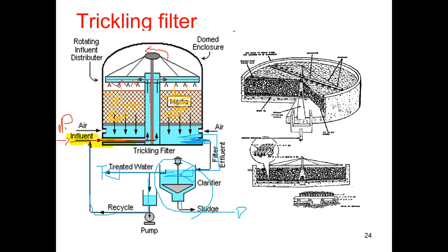And you know this is an aerobic biological reaction. That means there is organic matter, CHONS. Then microorganisms do the job with the presence of oxygen. So where is the oxygen? It is better to give additional oxygen. Here, this is the airflow. So by using a blower or compressor, we can provide extra oxygen.